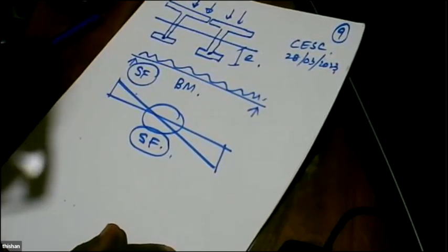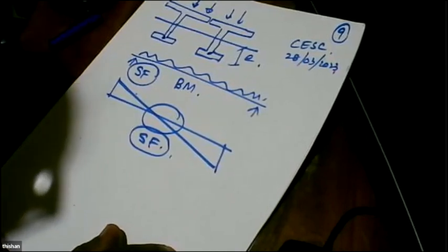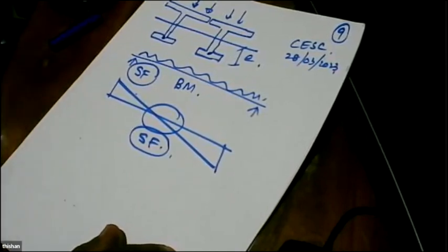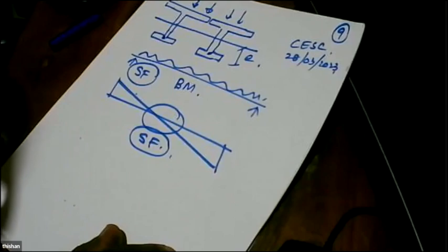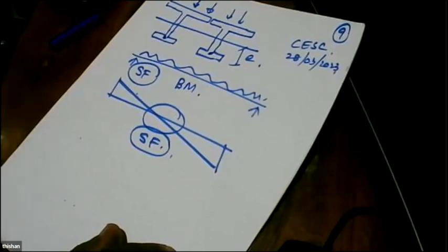Right? So always keep in mind, pre-stressed concrete means we must aim for as small a section as possible to maximize the axial pre-stress.